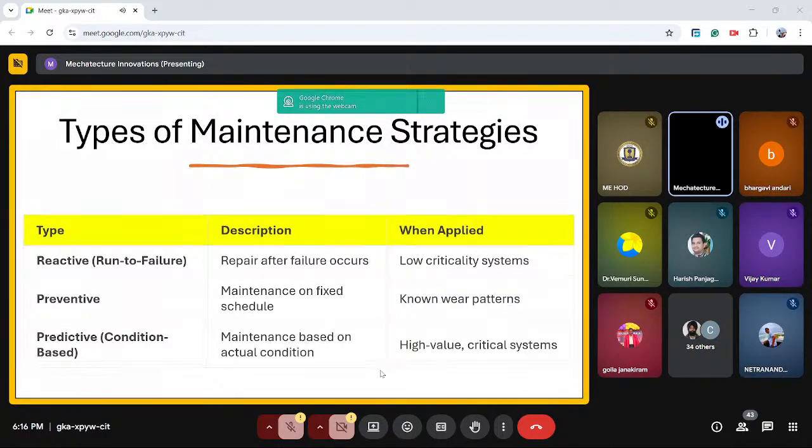In the same manner, using some machine parameters we are able to predict. So there are three ways: either maintain after the failure, or prevent before the failure, or even predict the failure. Condition monitoring actually falls under the second and third categories. I want to prevent the failure, number one, and also I want to predict the failure, number two. There is a very good saying in English that prevention is better than cure. So we try to predict and prevent, rather than try to cure through maintenance.